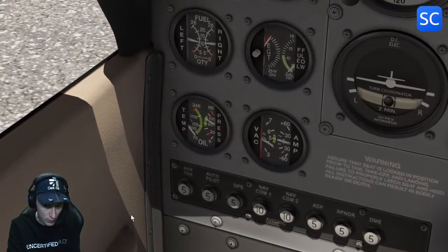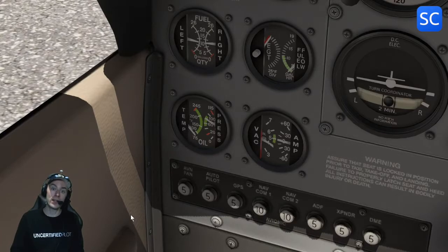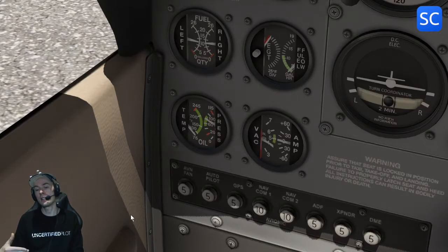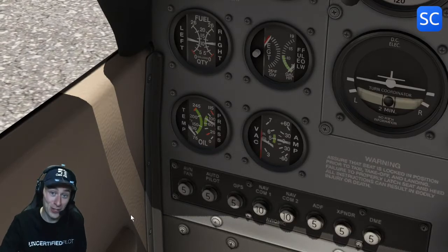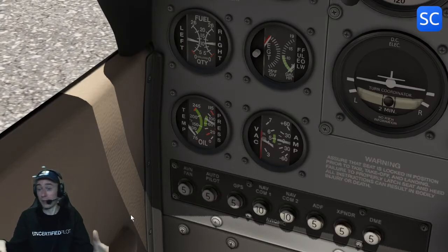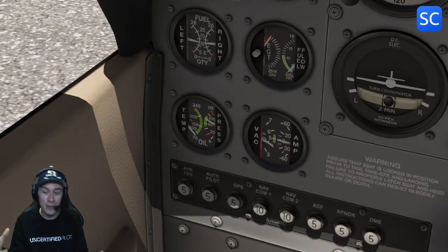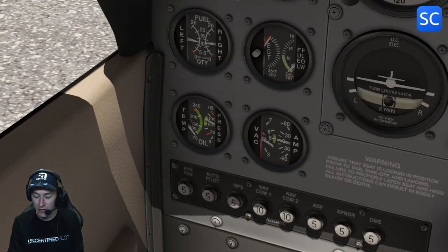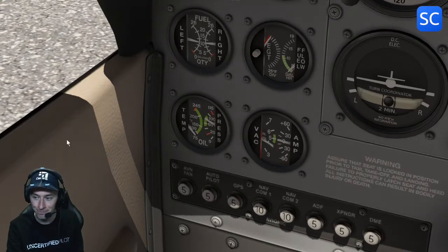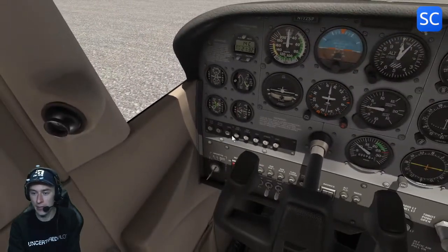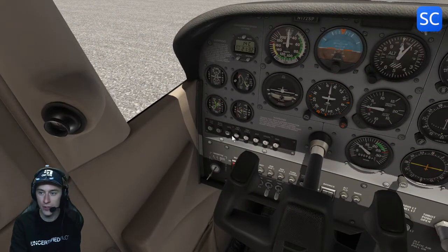Also very, very important. If we would already go into higher RPM without the engine being warm enough, we also damage the cylinders, and that will affect the flight performance. We will hear it, we will feel it while we're flying. It's a living and breathing thing, that aircraft with the rep, which I think is really, really great. So now at 75, we are allowed to start the taxi, not going higher than 1400 RPM or so.